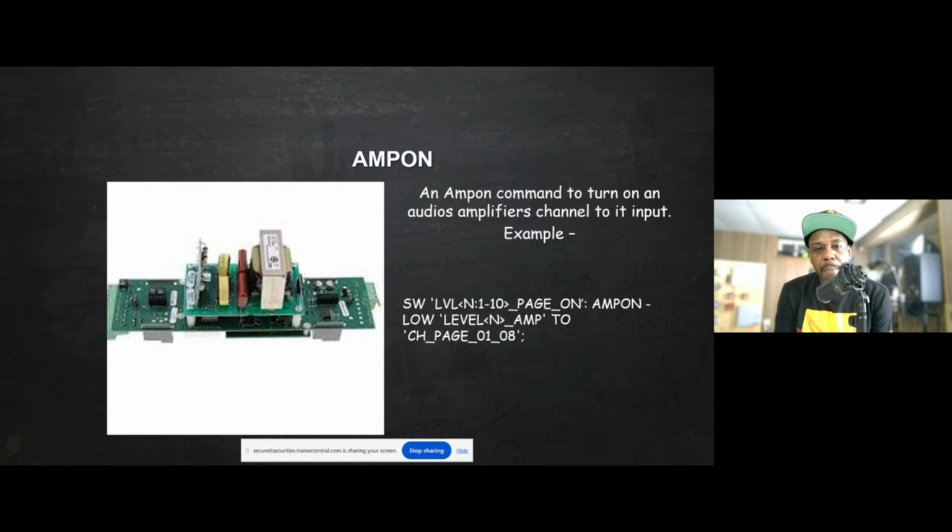We have on. If you're not familiar with high-rise buildings, assembly-type situations, or any large facilities that need some type of voice enunciation, this is where you would put the amplifiers in. If you have multiple amplifiers, when it comes to Edwards, you can write just one particular rule to activate multiple amplifiers and use that with the N variable. We'll go into the N variable when we start getting into the SDU in the coming weeks.